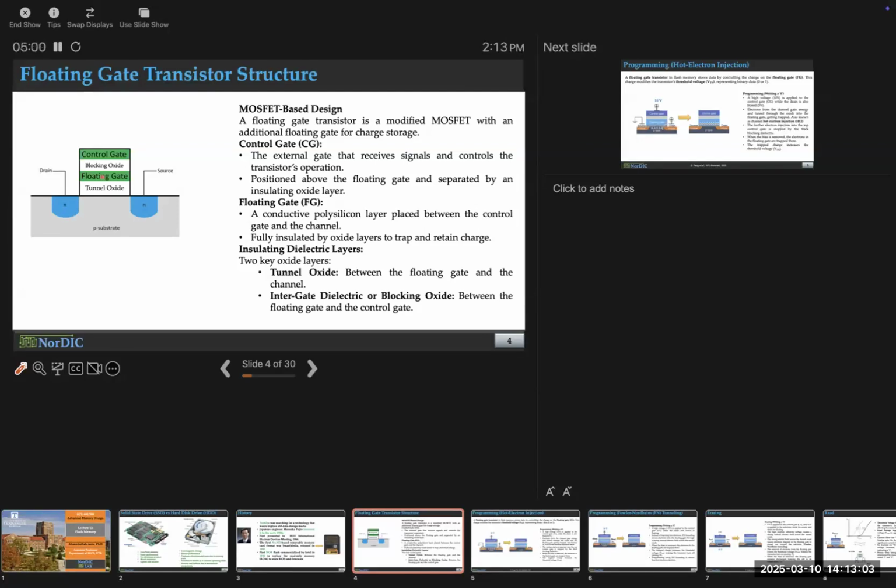That's not non-volatile. The moment you remove voltage, capacitors will just leak away all the charge. It's volatile, right? So how do you make it non-volatile? Why don't we make it in a way that we will trap the charges in a zone from where they will not be easily able to get out? So you basically put the charges in a prison, kind of like that.